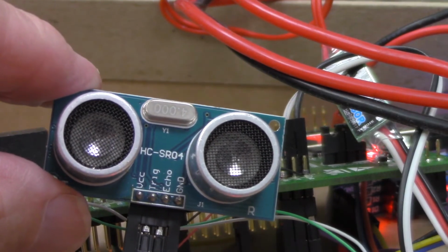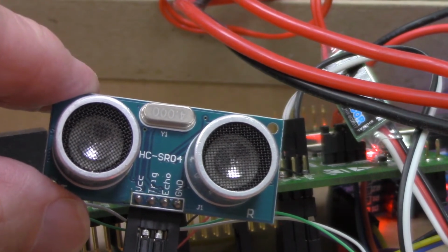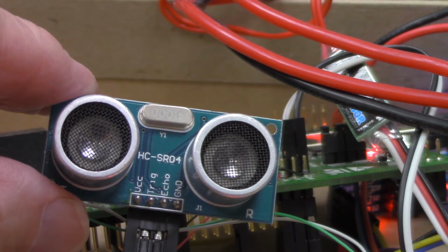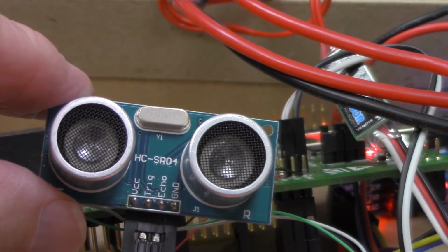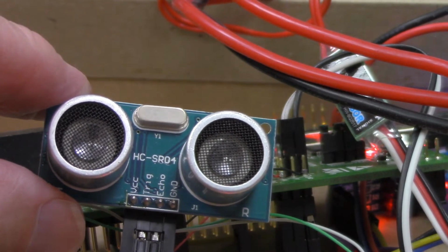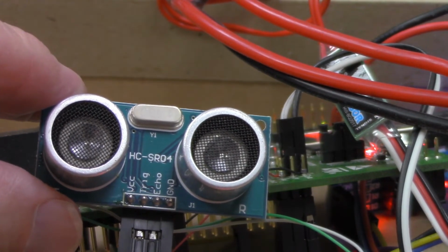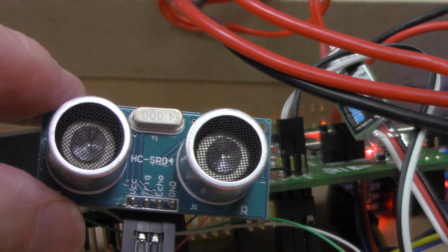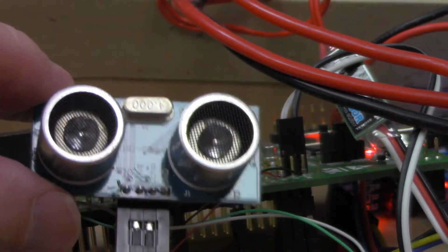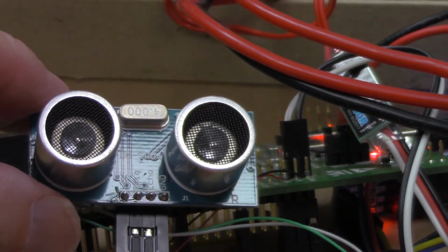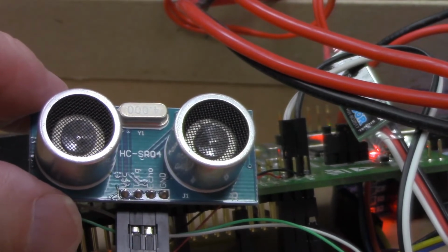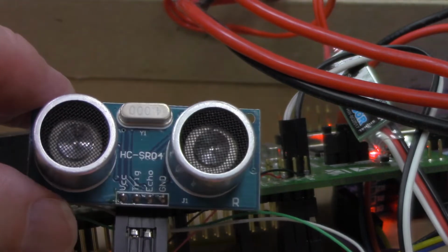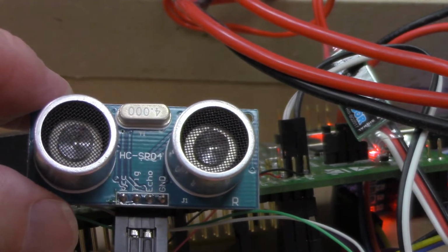So another thing I have is this HC-SR04 sonar, and it measures distance. I found it doesn't work very good with quadcopters because the sound of the motor seems to throw it off. But anyway, it does work for maybe possibly other applications. By putting my hand in front of it and away from it, I could get the distance to vary. So we'll take a look at that next.